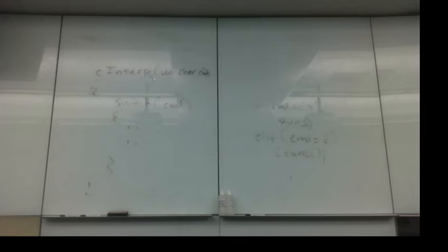Step 3 would be to enable any interrupts. And then step 4 maybe would be to configure the baud rate generator. You know, how fast the UART is going to send and receive data. And then the final step would be to enable the UART module, so then it's starting.